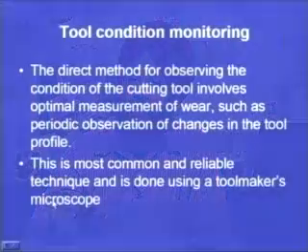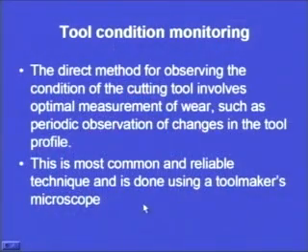So, that we will see after a specific set of time, and this is the most common and reliable technique, done using a tool maker's microscope. I have already discussed that the tool maker's microscope will be used to see the condition of the tool after a particular time of machining.